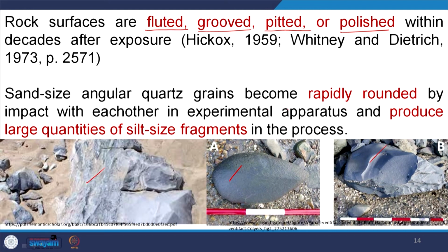So, by this process the angularity of sand decreases, and whatever material is removed from these angles, that is the silt and clay size particles. So, that means huge dust is produced. This process is called the abrasion process, that means during transportation the sand grains themselves collide with each other, and finally, they reduce their angularity and the product is sand, silt and clay.